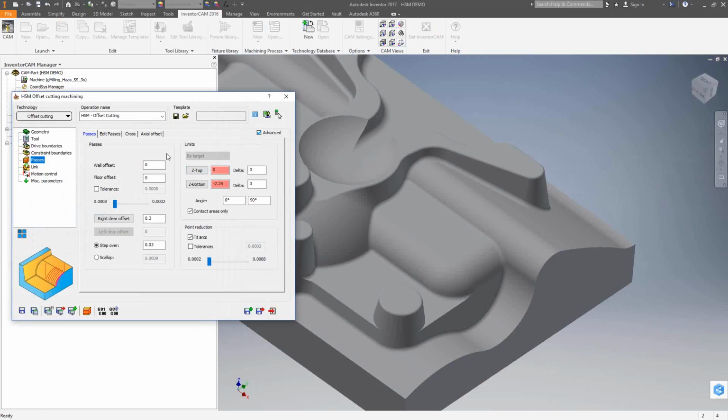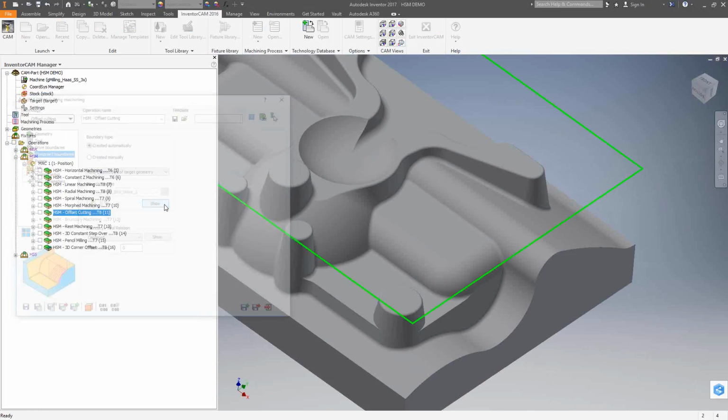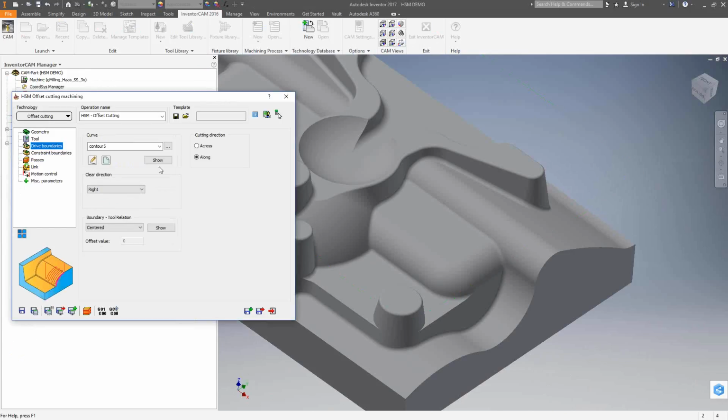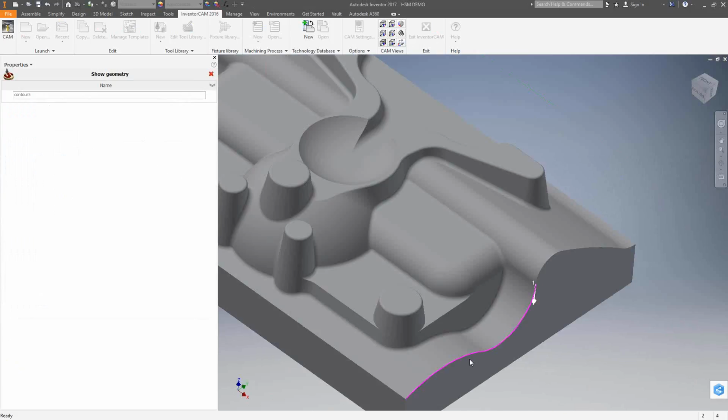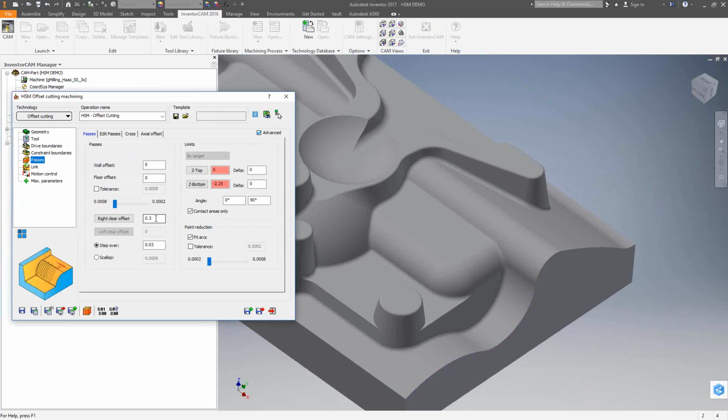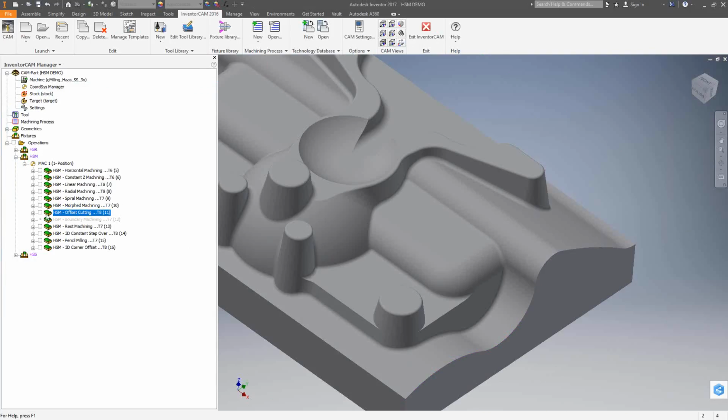Here, we're actually going to drape the clear offset toolpath over the part. I'm going to use the automatically defined constraint boundary, but under my drive boundary, I'm choosing just that edge right there. If we go to passes, you'll see that I've added a clear offset of 300 thou, 0 on the walls and the floor, full 90-degree spread, the same envelopes, with a step over of 30 thou. If we take a look at that, it is simply just a clear offset.